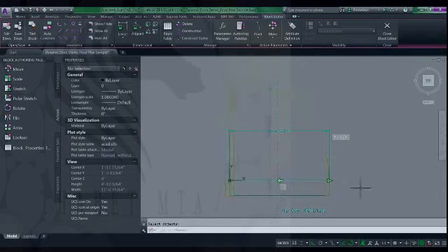I'm going to hit enter. And then as you can see, my action icon drops down by my impact zone for my flip. So I have that here. And now that I have my door panel and my door swing flipping either right or left, I want to associate what I did previously to this flip icon.